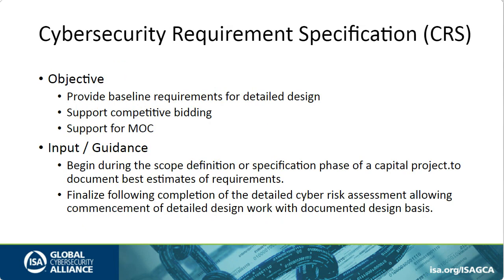Cybersecurity requirements spec. You want to provide the baseline requirements for detailed design. You can also use it to support competitive bidding. And it provides a baseline for management of change. If you're making a change and you have a documented basis of what you're supposed to have and why you're supposed to have it, then your management of change will be that much stronger going forward.